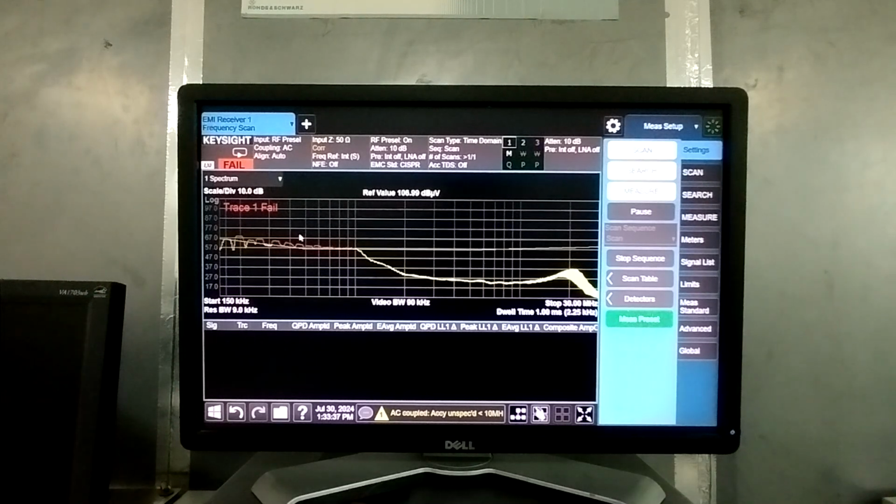It means that this device is not passing the conducted emission test for CISPR 32 class B category devices. I have selected this ViewSonic monitor on purpose, as I already knew that this device has some issue in its PCB. For demo purposes, I have attached this device to check the emissions from it.